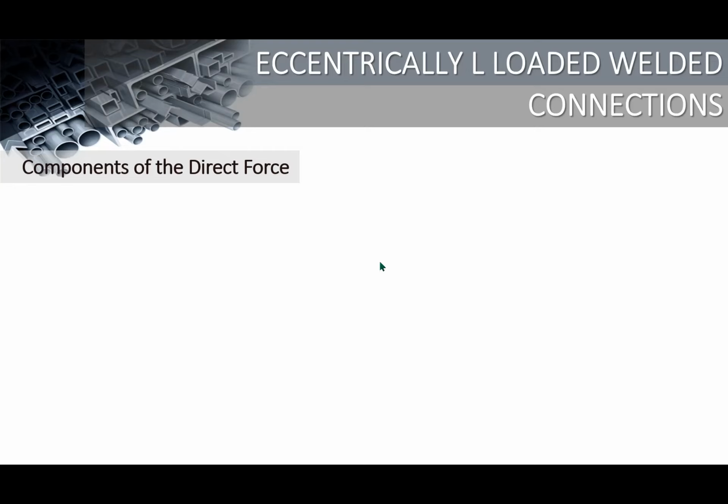But unlike the bolted connection, where we solved in terms of force, since this is a welded connection, we will solve it in terms of Q, or force per unit length. Since it's not just the direct force that we compute. By direct force, I mean in kilonewton. So the unit of our force is newton per millimeter or kilonewton per meter.